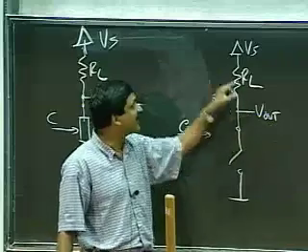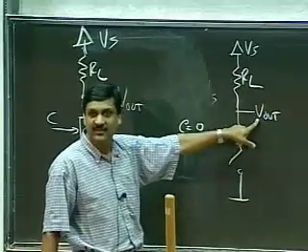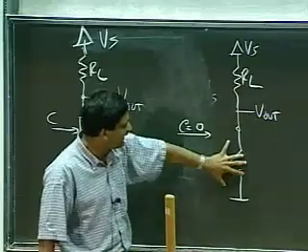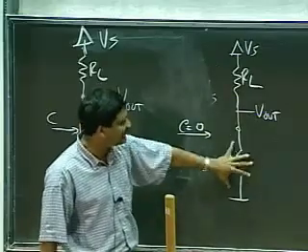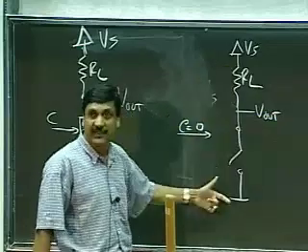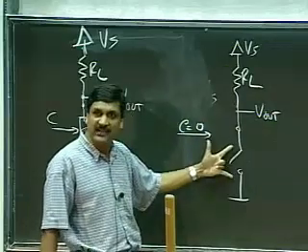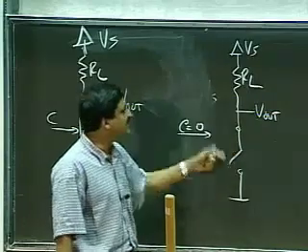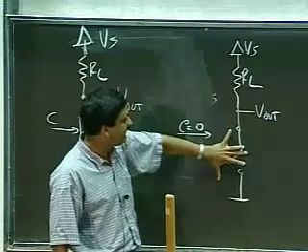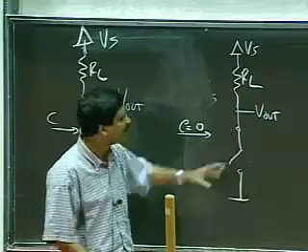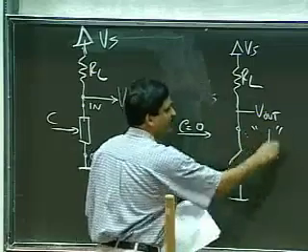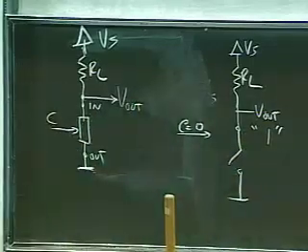Simple enough. This voltage Vs appears at V out because this is an open circuit here. Remember, RL and this little device form a voltage divider, but since it's an open circuit, its resistance is infinity, and so in this resistive divider, all the voltage falls across this open circuit. So in this case, V out is a 1, or a high. We get a high voltage.